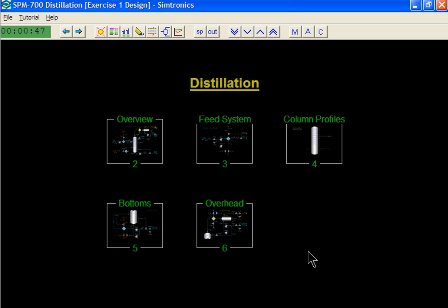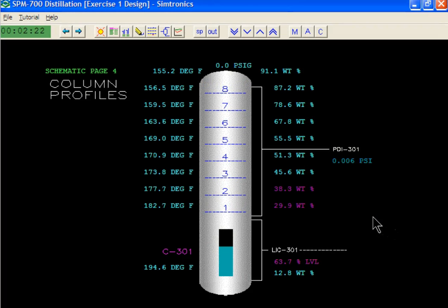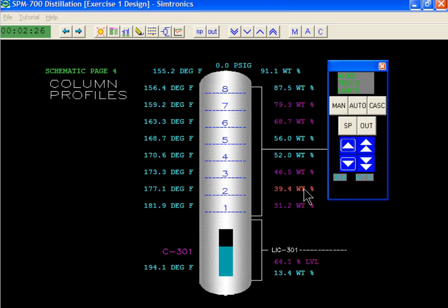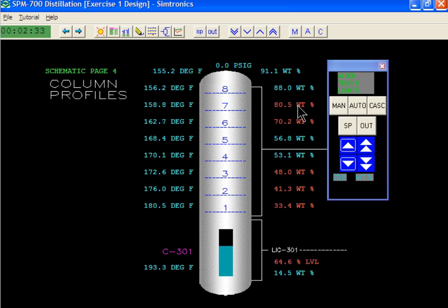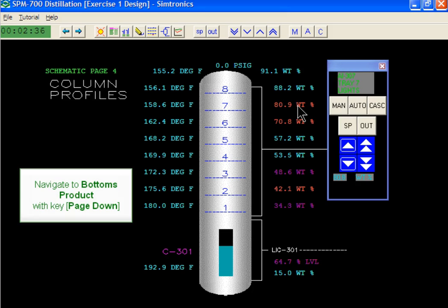Responding directly to a key process variable that is in alarm may not always be the best corrective action. Understanding and observing the relationships of all process variables can help you troubleshoot the problem and take proper corrective action to return the process to design conditions. For example, reboiler fouling might be the cause of column temperature, pressure, composition, product flow rate, and level alarms.